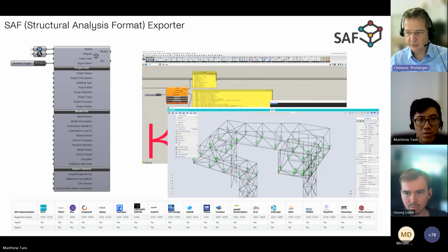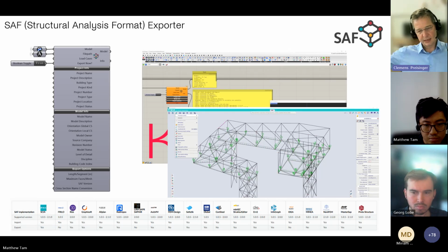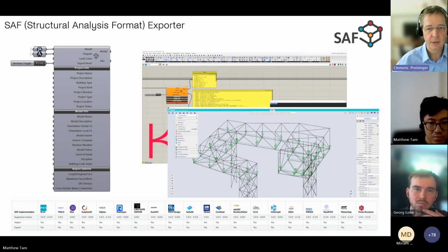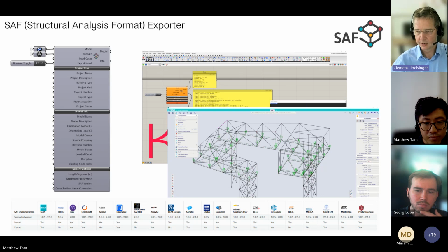Then, is pre-stressing possible in Karamba? Yes, it is. There's a load type which is called pre-strain. So you can pre-strain elements and thereby introduce post-tensioning of elements. And it's also possible to impose prescribed displacements on supports. So this could also be used to pre-stress structures.